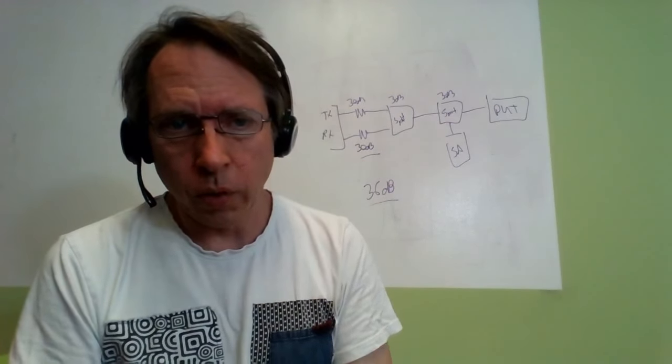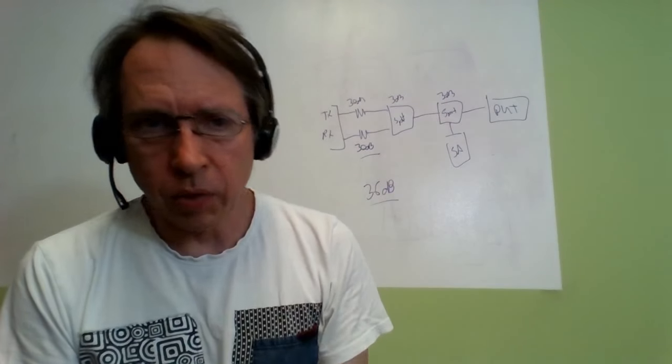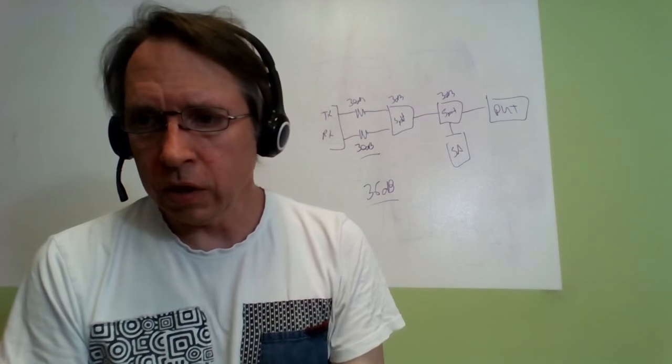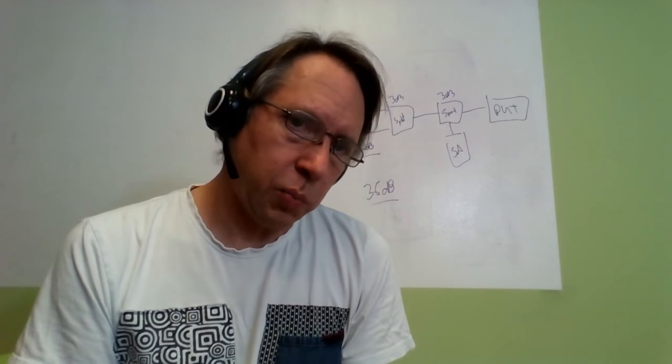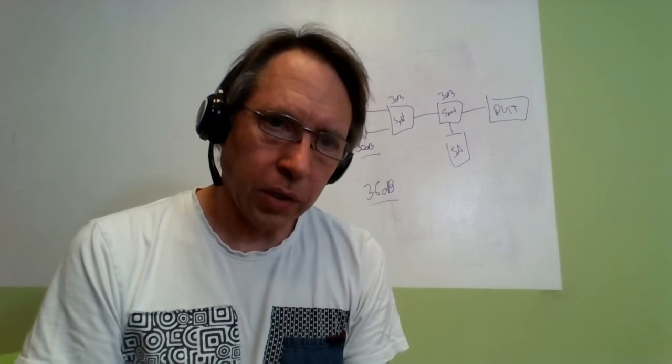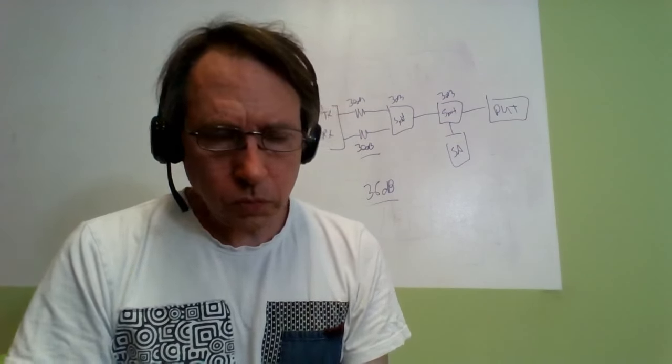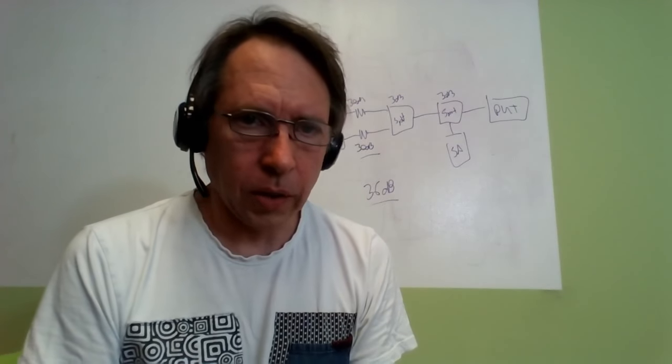The way the LabKit is configured right now and the test fixture that we're using, we would actually expect the device under test to report back an RSRP of somewhere around negative 80. So we know that this connection is okay.